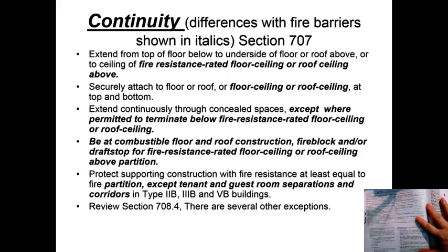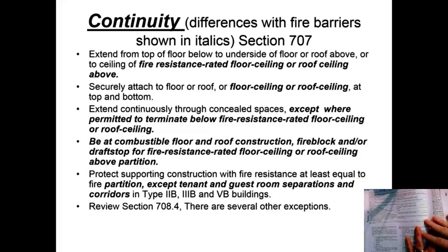That means the walls, the doors, everything that you're looking at is 1 hour, or provide an automatic sprinkler system. You're going to see the codes are moving more and more toward having sprinkler systems everywhere, and that would solve a lot of problems. But a lot of times you will find that your clients don't want to spend the extra money for sprinkler systems. But sprinkler systems are required in just about all buildings today.